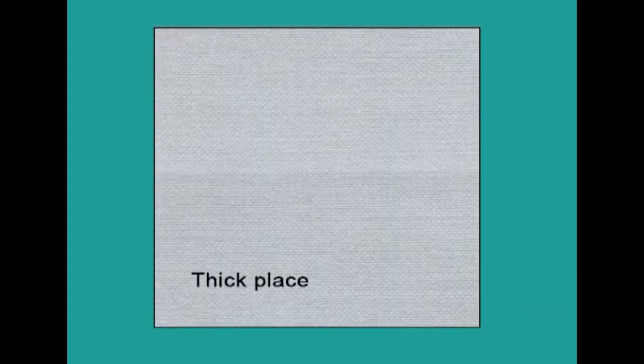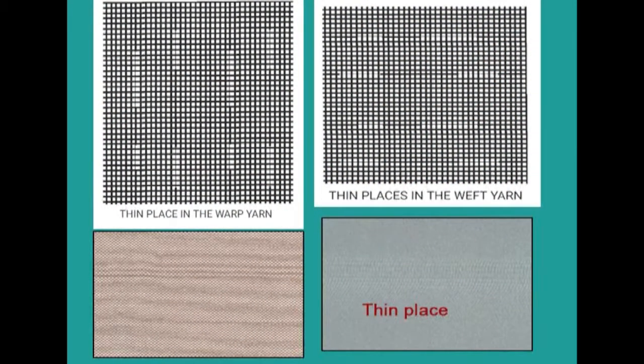And we have thick places, a prominent band in which an increase in stitch density compared to the rest of the fabric is apparent, and sometimes it is taken as a minor one. And if you have thin places in the fabric, this is also a defect, often caused by the filling yarn breaking while the loom continues to run until the operator notices the problem, so it can be considered a major defect.